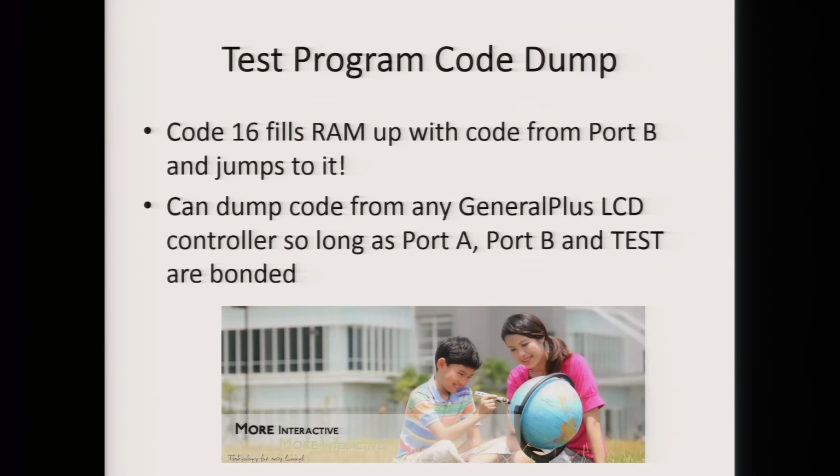So that's pretty cool. That basically means that there's now a method you can use to dump code from any General Plus LCD controller. The caveat being that port A, port B, and test have to be bonded. So on some chips, you might actually have to remove the epoxy. But this can always be used to dump the code, which I thought was pretty cool.